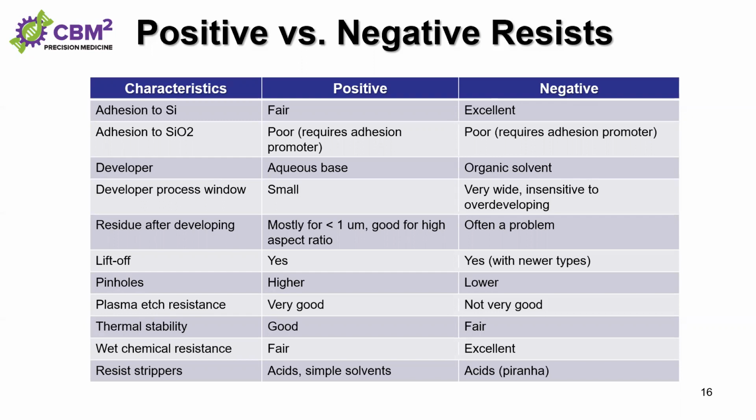In particular, when you use a resist like SU8, it's very difficult to remove the SU8 after the process. For example, with positive resist, you just put it into developer and it's gone. For negative resist it's possible, but you need more expensive equipment to remove it.